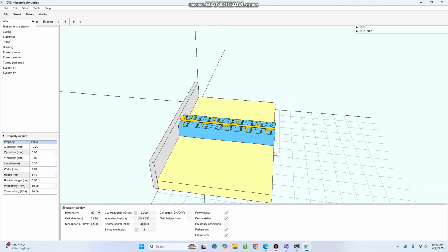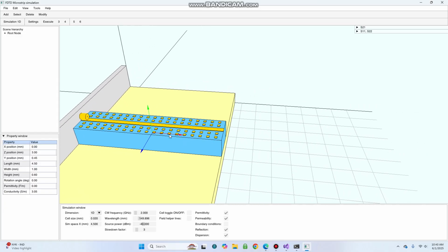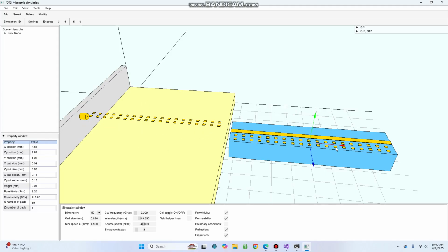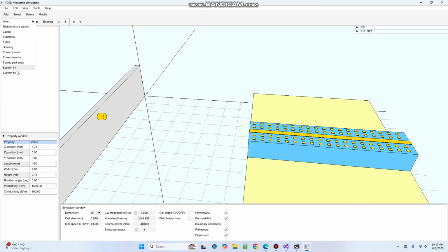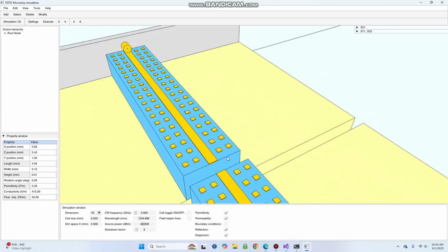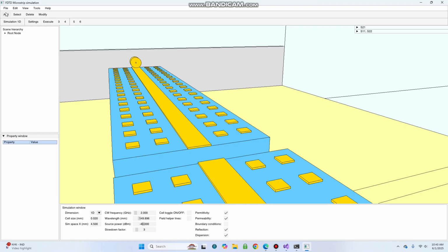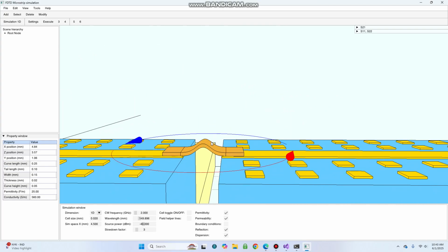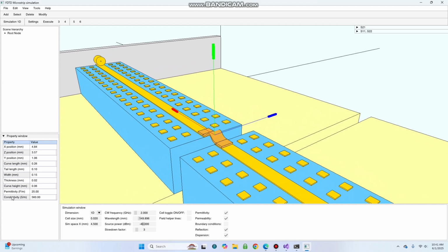And you can actually make more complex constructions by moving things around and rotating them as you'd like. So for example, you can move this a little bit to here, put the carrier underneath, and generate the same thing. And then to connect the things, you can make a wire, a ribbon, as an interconnect. So you can put something like this, and you can also control the height of the ribbon and also the size of it, and of course the physical properties such as permittivity and conductivity.